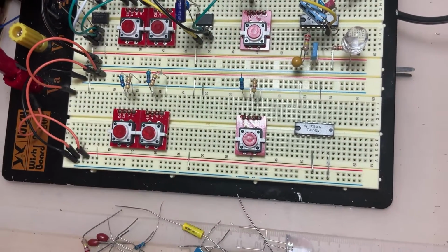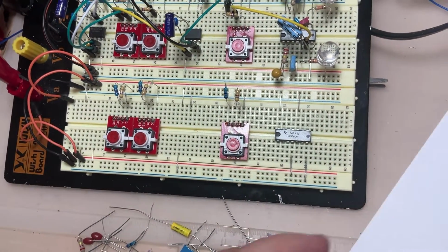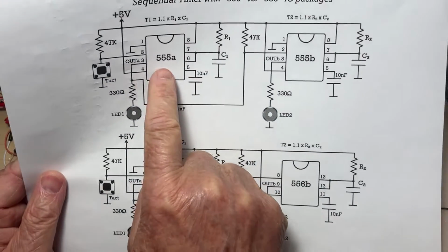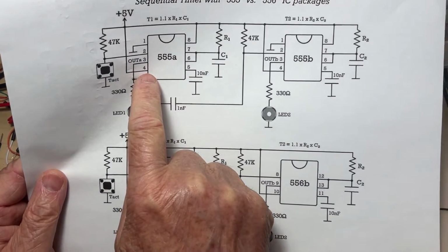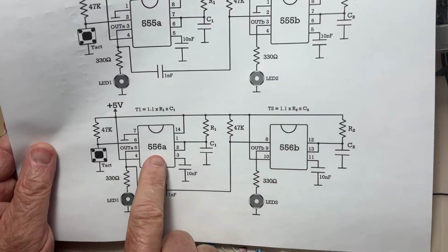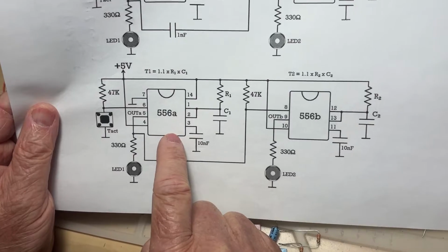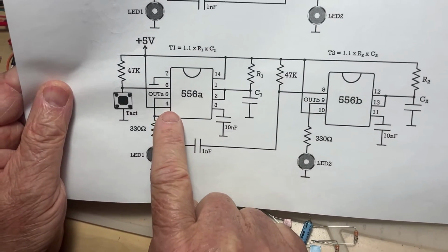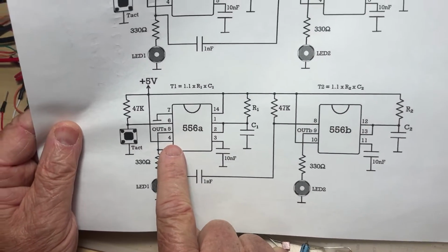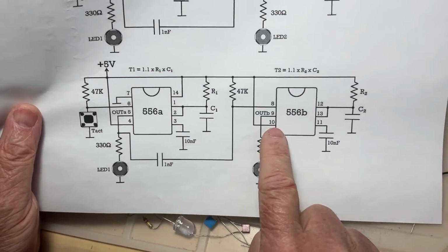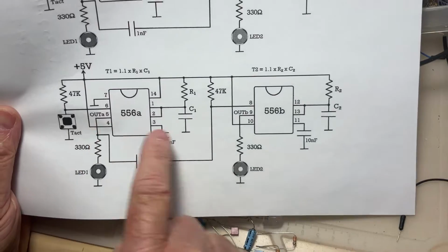And then if I take a quick look on the diagram here, I don't need to use the reset terminals. So unlike the 555 where the reset is on the pin 4, this time for the first half of the 556, so the first timer, it is going to be the pin 4 exactly like for the other one for the first half package, but it's going to be the pin 10 for the second half. So the pins 4 and 10,